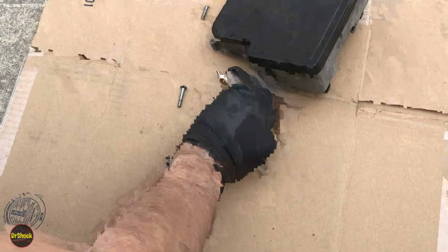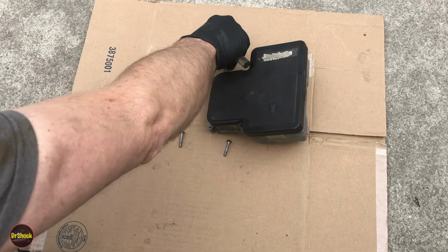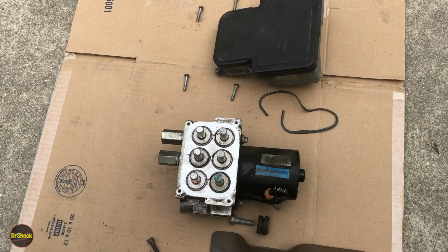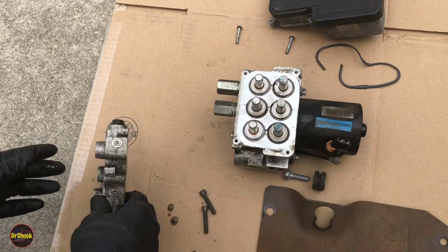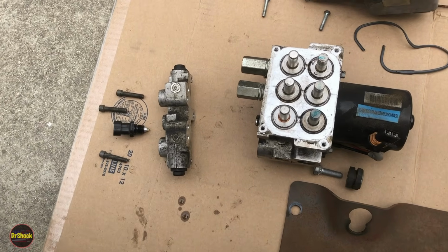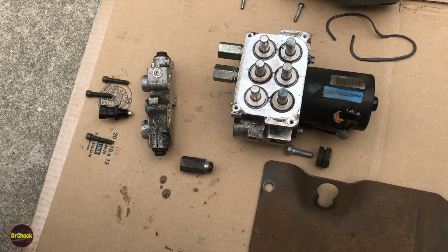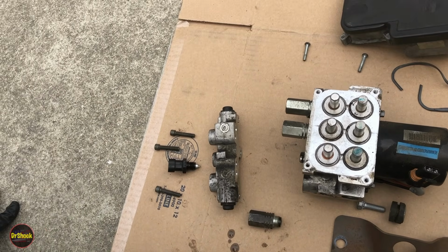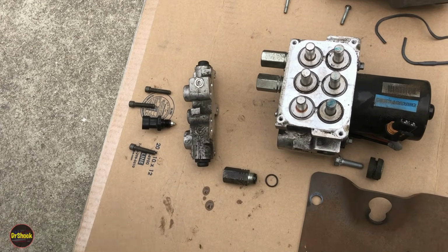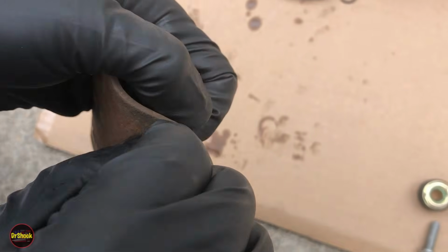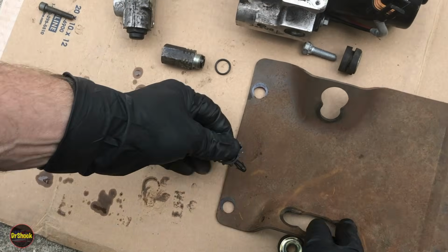So we've got these four bolts here are torque to yield type, so they have to be discarded. We've got our gasket. We've got our combination valve. We've got our pressure switch. We've got our 3 Allen bolts. We took off one of the 3 connecting tubes here. Trying to find our little O-ring that went flying. We didn't take this out, but if we wanted to, just give it a pinch, and that separates out from the bracket.